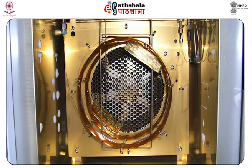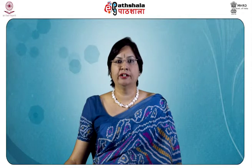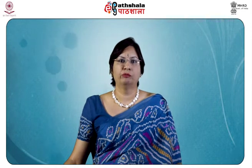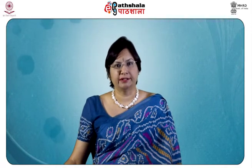If it is for petrol or gasoline, it starts at 70 degrees centigrade, is kept isothermal for 5 minutes and increases at 5 degrees per minute up to 120 degrees centigrade. So, the range is you keep it from 70 to 120 degrees centigrade. Now, if the same process is being done for kerosene, then the temperature starts from 90 degrees centigrade and continues at 10 degrees centigrade per minute up to 220 degrees centigrade. The range is 90 to 220 degrees centigrade and the hold is for 5.5 minutes at 220 degrees centigrade.